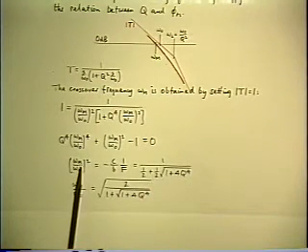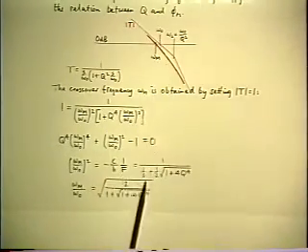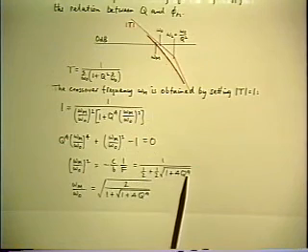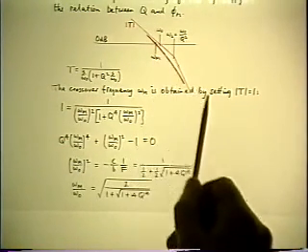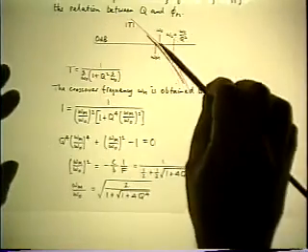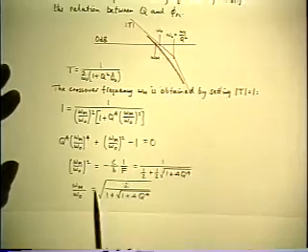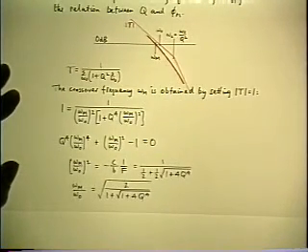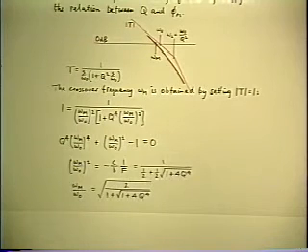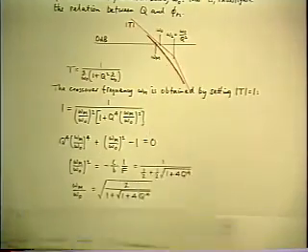So this is the result for the crossover frequency relative to omega 0 as a function of Q. Check that it goes to omega 0 if Q gets very small, because if Q gets very small, this corner moves off to the right, and omega m ought to approach omega 0, which it does. If you let Q go to 0, the ratio goes to 1. Okay, all that's left now is, now we have solved for omega m in terms of the position of the second pole,